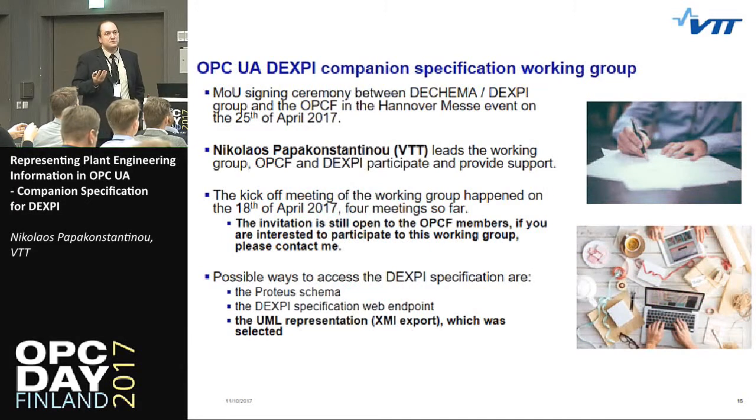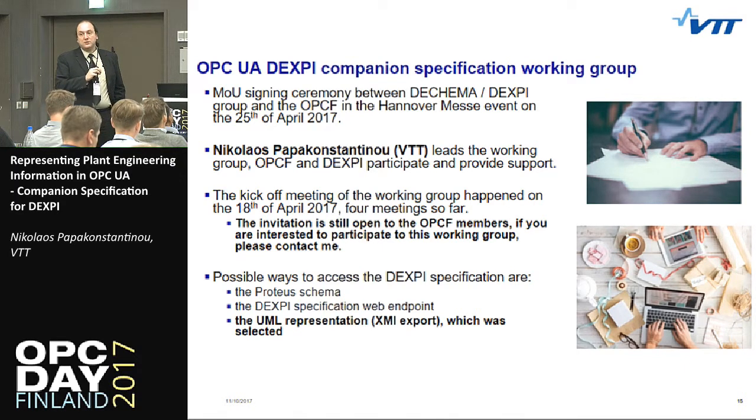In that context, we started an OPC Foundation working group to build an OPC UA companion specification that will describe how piping and instrumentation information, which follows the DEXPI specification, can be expressed as OPC UA node sets, which can then be used to offer them using OPC UA servers.